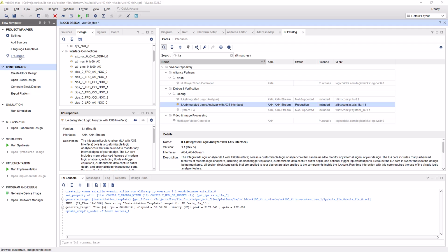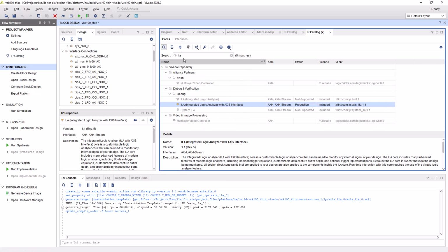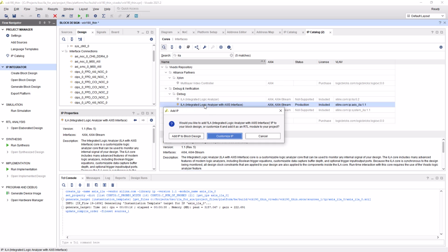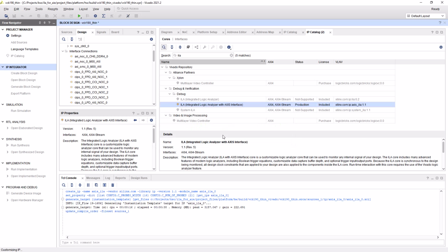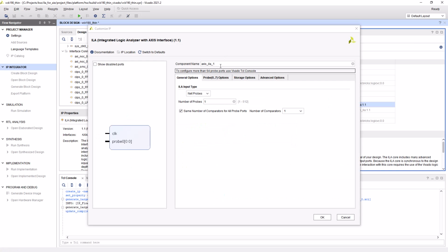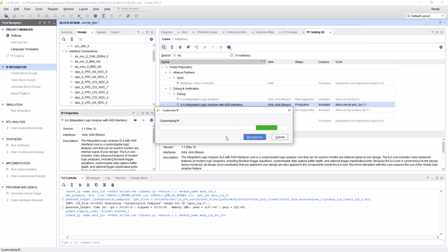Another way to add signals using Vivado is to generate an instance of the Axis streaming ILA from the IP catalog. You can then instantiate that instance in your RTL. This can be useful in debugging AI engines if the RTL code interfaces the AIE array.